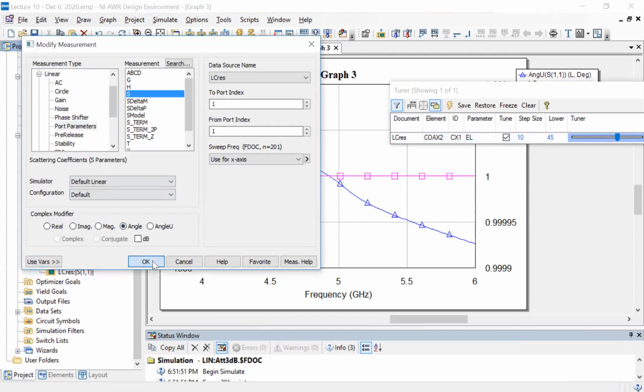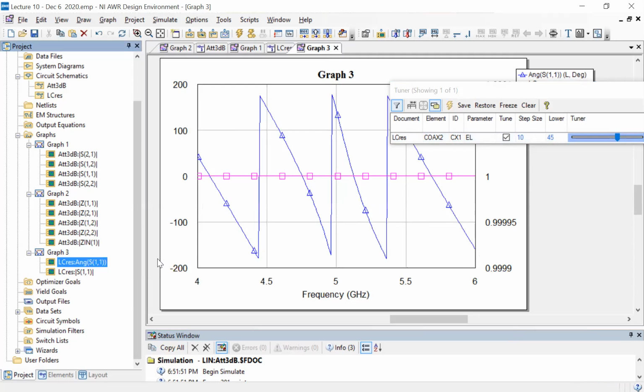And this can be done simply because this is just a mathematical change by adding this electrical length, which essentially cancels this out. It says that, okay, if there was an additional length of this type, I'll just add a phase as a function of frequency and cancel it out to get rid of this. But there is nothing happening in the magnitude, as expected, okay?